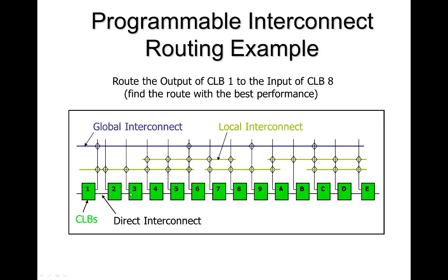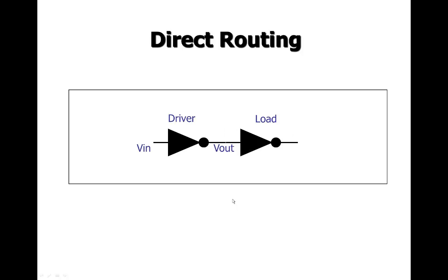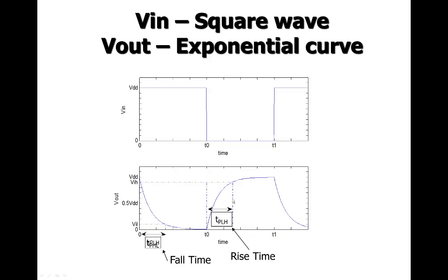So the place and route tool is trying to minimize the delay for communication, and so placement of your logic in these CLBs can determine that, and also the routing. So here we can show that with a global interconnect, one here can go talk to, then using a local interconnect can actually go talk to 8, for instance. Okay, we'll talk a little bit about routing delays.